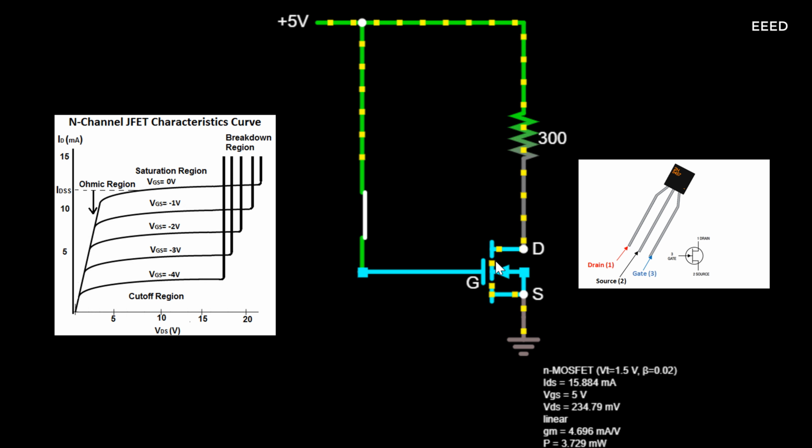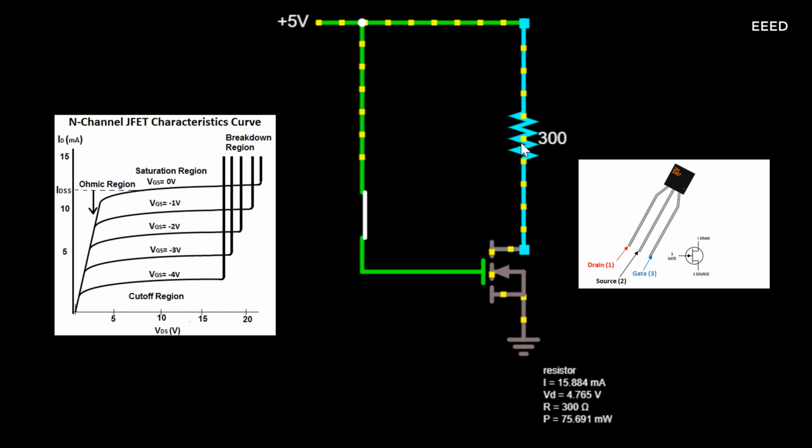You can see based on this N-channel JFET transconductance curve that as the negative voltage to the gate increases, the gain decreases. You can see that the gain, the current ID output by the transistor, is highest when the voltage fed to the gate terminal is 0V. As we increase this voltage negatively, again, as stated, the gain decreases.